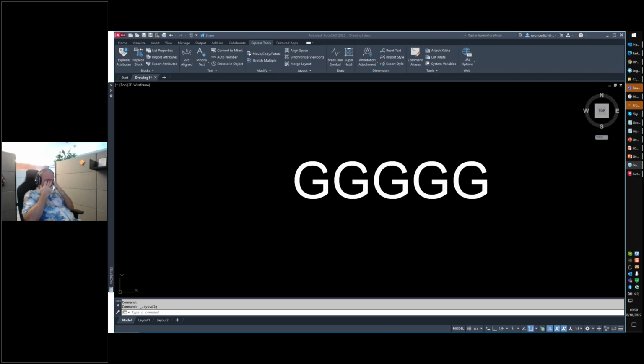One of the things I commonly find is that if you end up with an invalid block definition, it's going to crash your CAD every time you open it up. And then you have to do BLOCKMRU to clear the block most recently used. And then you have to go and edit the libraries, and you can point to multiple libraries, but it will always be creating that metadata for your previews and things like that.